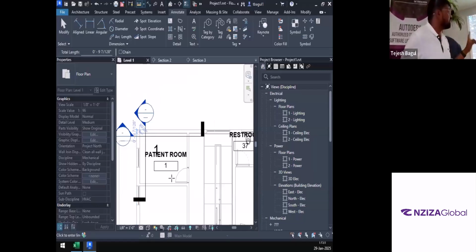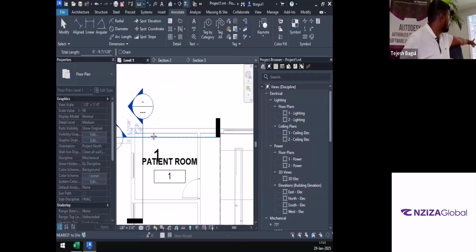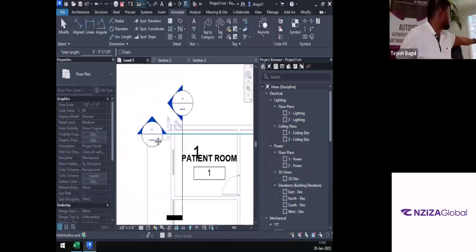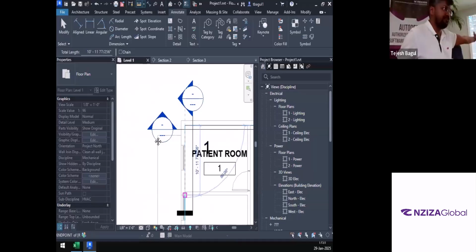All right. So over here, it is not the area that we are looking at. We are looking at the lineal foot or lineal meter, whatever it might be. We are looking at length, not the area this time. So over here, the length we will check from here to here. It was around 12 foot, right? And then from here, around 10 foot 6 inches. So 12 foot plus 10.5, 22.5, correct? 22.5 foot is what our crack will be for that particular wall.